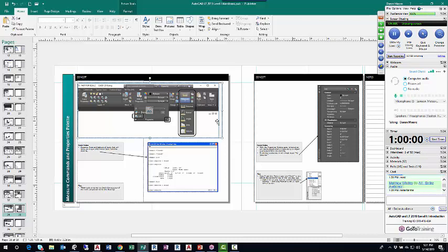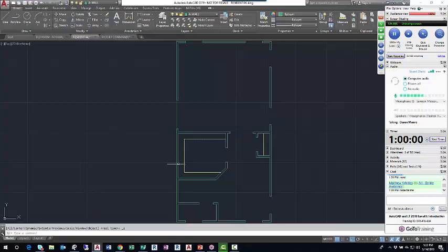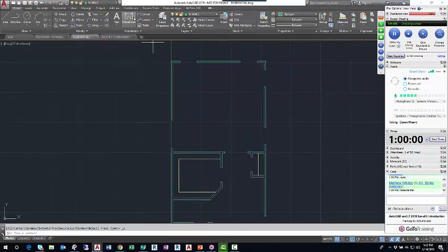Nice, okay. So one more thing here, and you saw this earlier on page 34, is the list command is highlighted. I used list earlier today. I'll just use it one more time so you can see it. Say I want to know the area. I'll find a rectangle. I'll create a polyline inside of the big bedroom area.